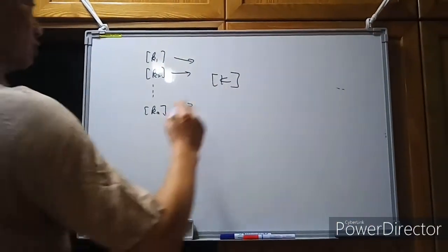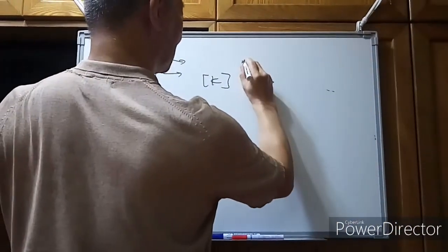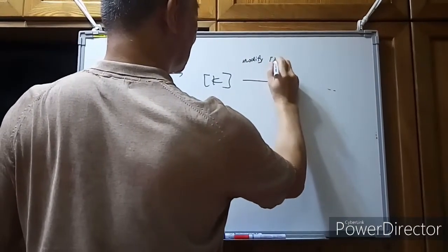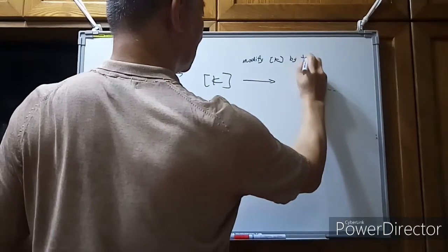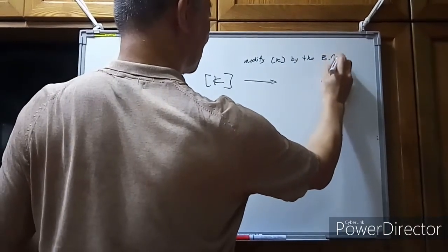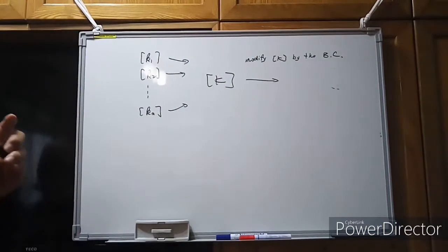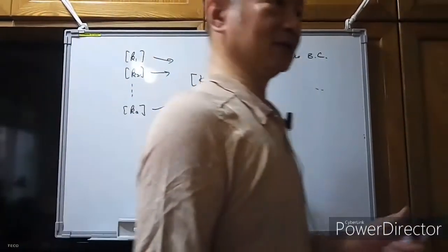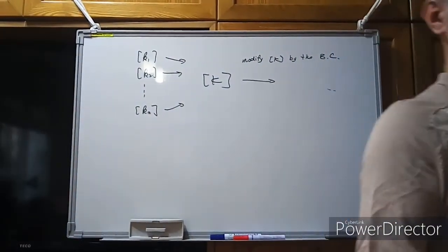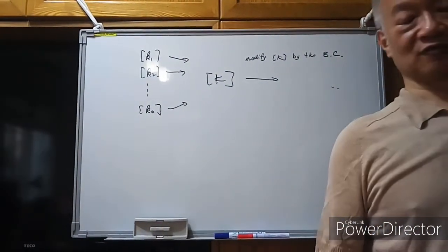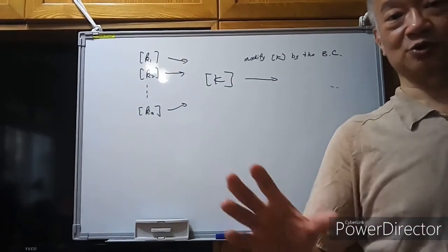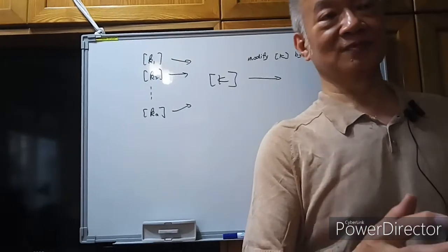And the assembled global K matrix, we need to modify by the boundary conditions. Remember we will not consider the boundary conditions at the beginning in the derivation, since if we consider the boundary conditions, then there are several special cases for some elements.